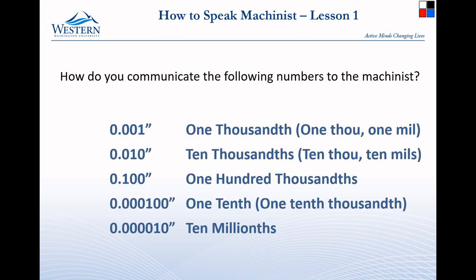So if we want 1/4 of an inch, you can call it 1/4 of an inch, but it can also be 250 thousandths. One reason that we leave it as 250 is because then we can do math more easily. If we start going to 1/4 and then you have to add 14 thousandths to it, then it starts to get confusing. 250 plus 14 is pretty quick and easy to think about. And so we will often just always think in thousandths in the shop. Questions about that?